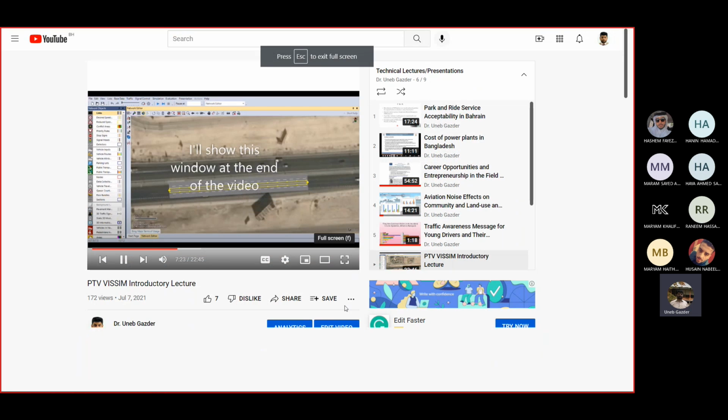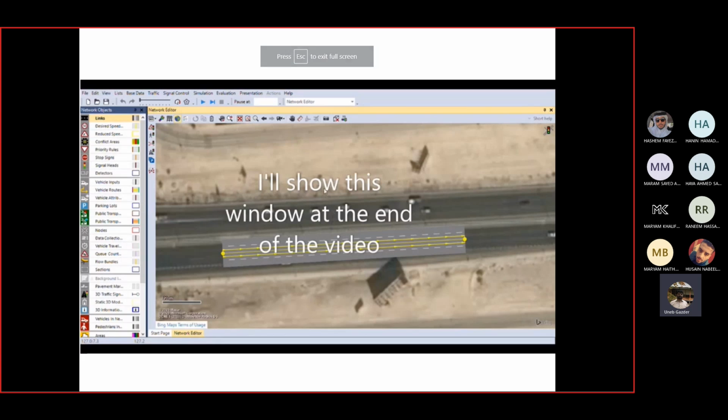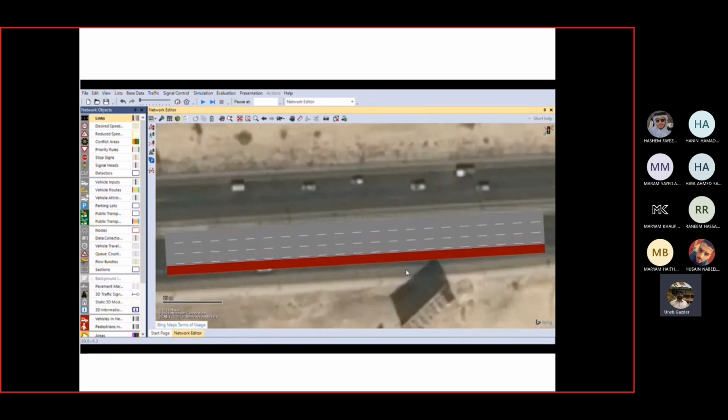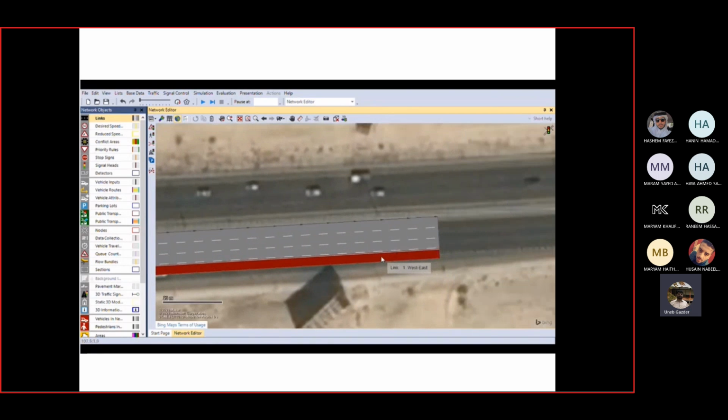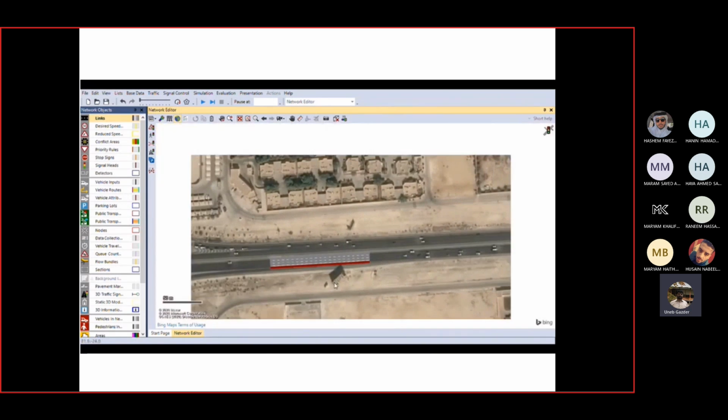Lane, because that will not be part of our simulation, and you can change it to obstacle, for example. So we'll put no lane changes, and that'll have blocked our shoulder lane from being used at all. Now, in the case of widths, you can measure these from Google Earth. I measured mine to be 3.5 meters for each road lane, and for the shoulder lane, it was only 3.2 meters. You can enter that over there and go ahead and hit OK. Now automatically your road is there, 4 lanes, with the shoulder lane being a little bit smaller.